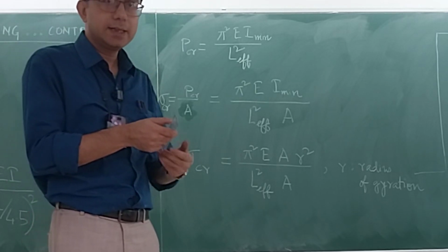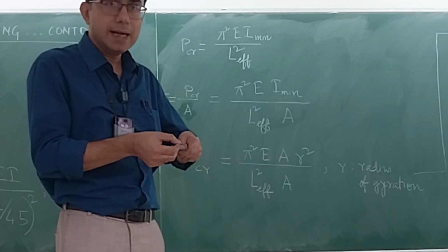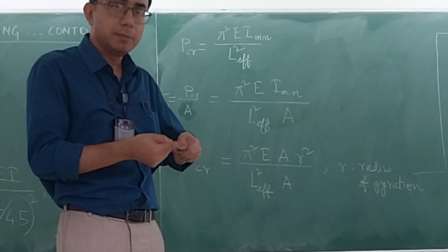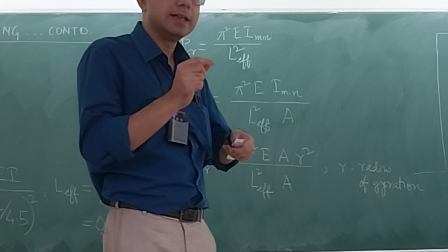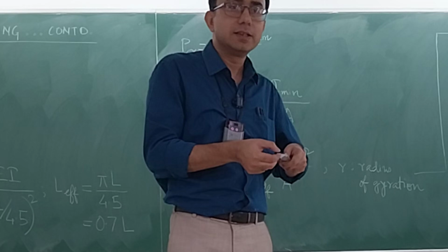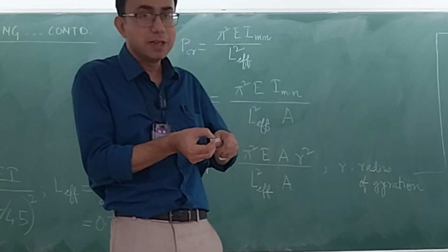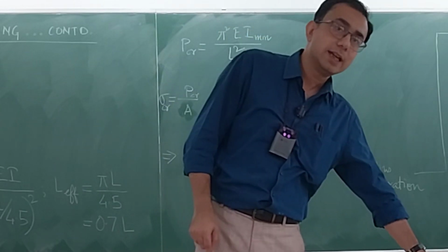But if you take an axis like this, you see there is barely any material above and below the axis. So the formula is 1 by 12 b h cube, right? The h cube is there, but it is barely contributing anything because within that 1 millimeter, it's like 0.5 above and below the axis.